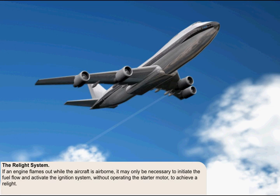In the event of an engine flaming out while the aircraft is airborne, it may only be necessary to initiate the fuel flow and activate the ignition system without operating the starter motor to achieve a relight. The starter motor should not be required to rotate the engine in these circumstances because the engine should already be windmilling.